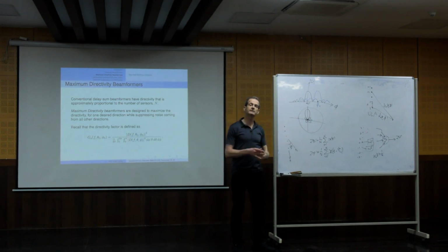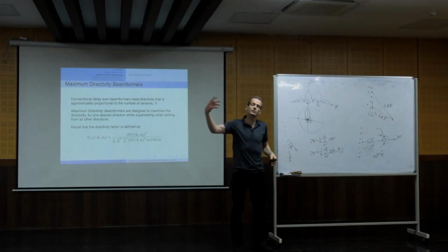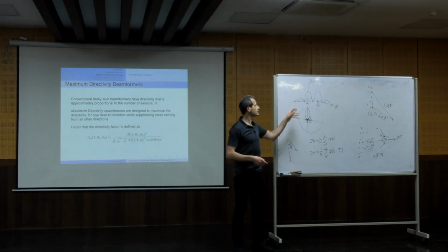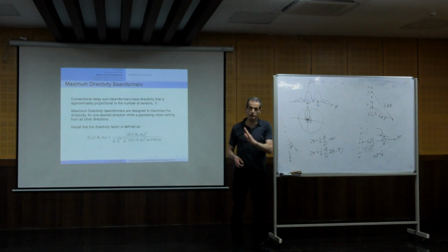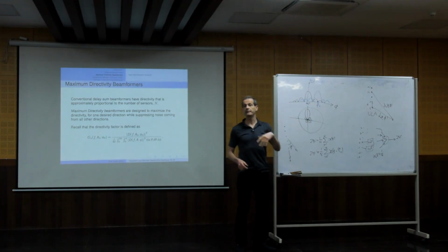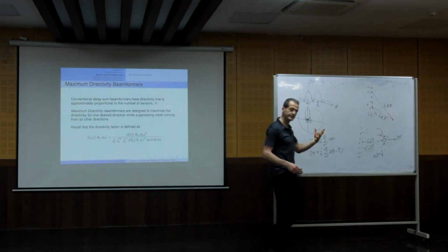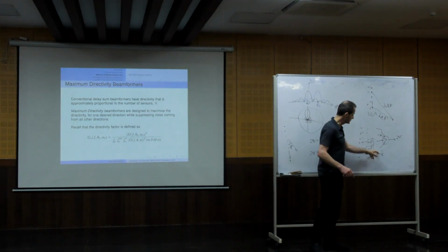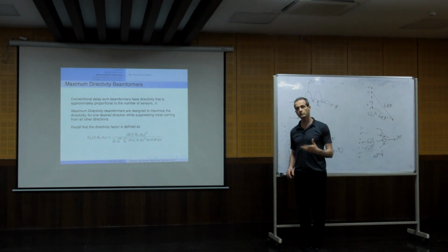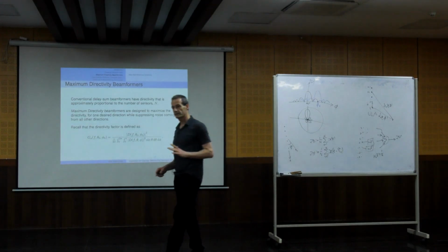So suppose that there is a source that comes from a certain direction and you want to put a null. This is also called null beamforming. And you want it to remain in the same direction for all frequencies. And maybe you want to keep the side lobes the same, independent of frequency. So it's possible to design, and when I say design a beamformer, it means how to design these weights, such that the beam pattern will be frequency invariant.